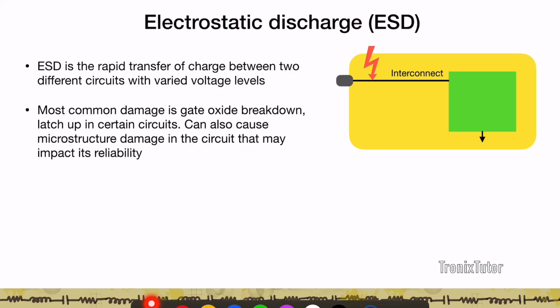And one of the most critical dielectrics in our circuit is obviously the gate oxide. So if this happens across a particular gate oxide, right, then all of a sudden the MOSFET gate, which was insulating, can end up being conducting, right? And so in that case, there is a leakage current that goes from the gate into the source or the drain. And that can cause a failure on the circuit.